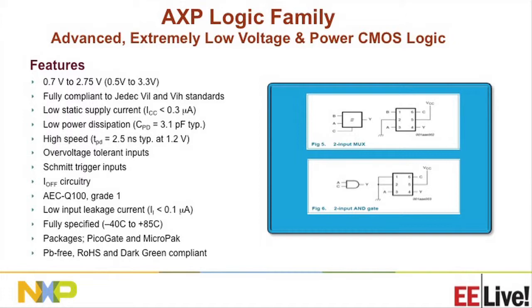And the first device that we did in this space is the configurable logic. So later on, we'll see how you can configure one device into any of 7 unique functions, and that's what the configurable logic is. Like other logic families, AXP logic is automotive qualified. So that means we operate up to 85 degrees Celsius by design, and you don't pay the premium for that.